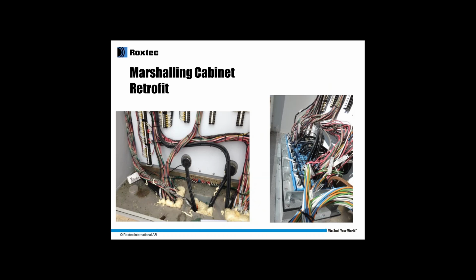And here are a couple pictures of a project we worked on where mice had actually chewed through the foam to enter the cabinet and then caused damage to the wires. So we created a mounting plate and used one of our openable frames. That way we could actually seal around the cables that were still usable and they didn't have to take everything apart. And this is going to protect the cabinet from any further future damage.